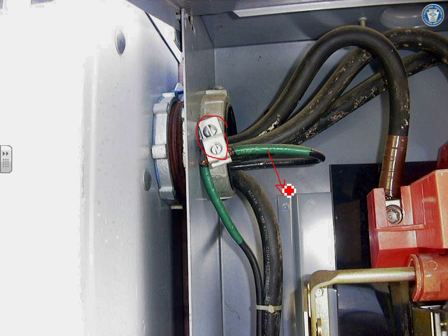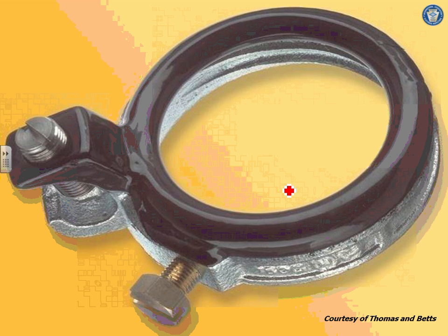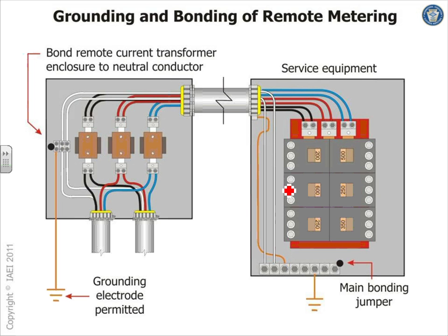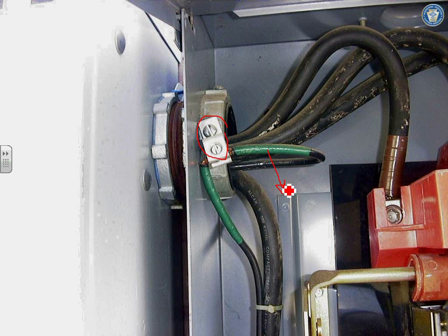There are also clamps that a lot of people use, external clamps, and I'm sure a lot of you guys have EMT conduits coming to a box, three of them paralleling. You take a clamp, 1, 2, 3, you daisy chain them and take them to the grounding bar. So bonding bushings, that's what I thought, especially the material. I'm sure you guys have encountered them and you see them all the time. Any comments, any questions?